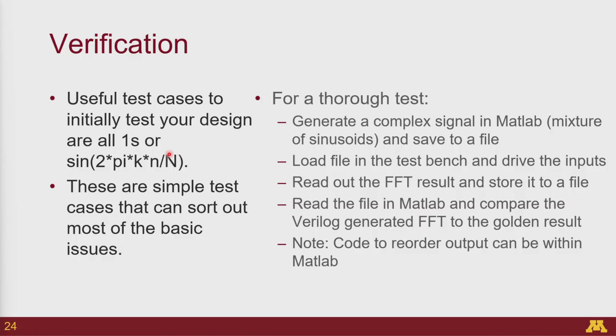For a more thorough test, when you finish your design and have verified simple functionality, and everything looks fine, what would be a more thorough test? Something like a mixture of sinusoids. Say, for example, you mix 3 or 4 sine and cosine waves of different frequencies. What you can do is create something like a MATLAB script to take these values and then generate the output.